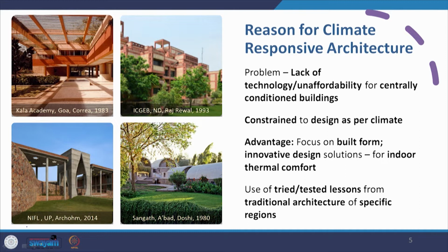So if I'm making it hot and dry in Rajasthan, or I'm making it hot and humid in Mumbai, or I'm making it composite in Delhi, or making it in cold conditions in Kashmir, I have to keep the climate in mind. So therefore, the building based on this would be very region specific. It would be a modern building, built for a modern use and a modern generation, but it will respond to the local climate. That in itself makes it a critical regional building.